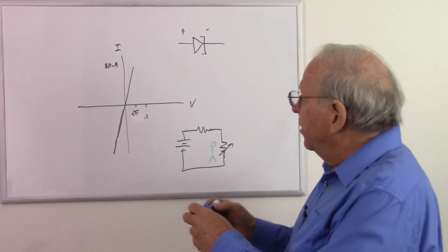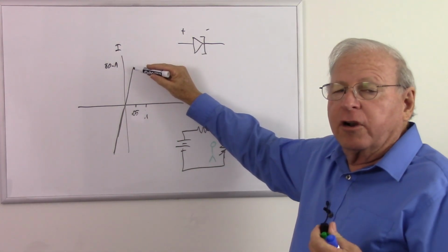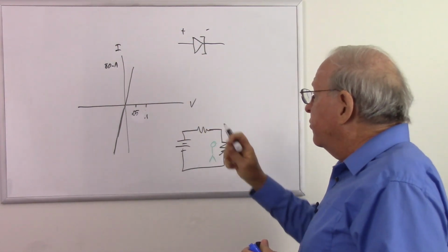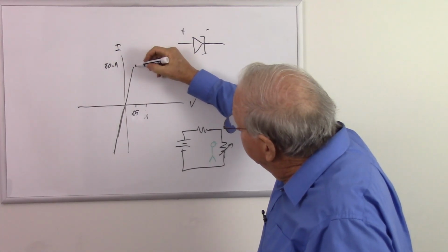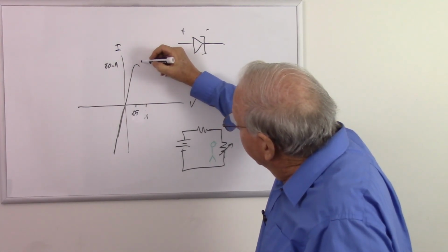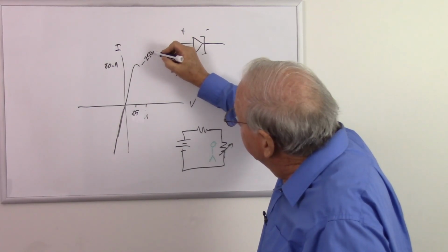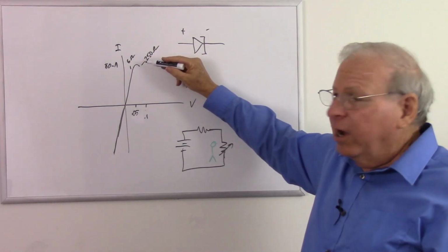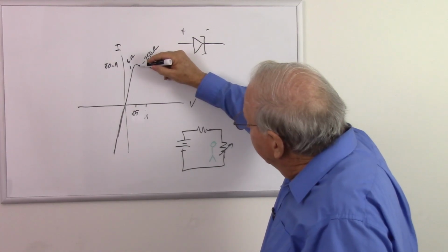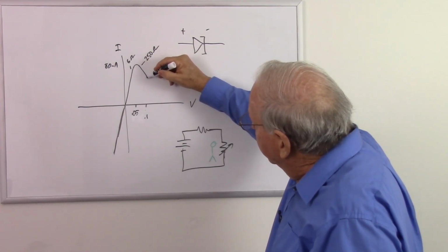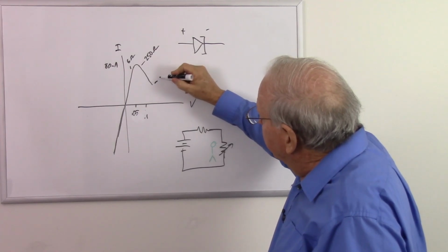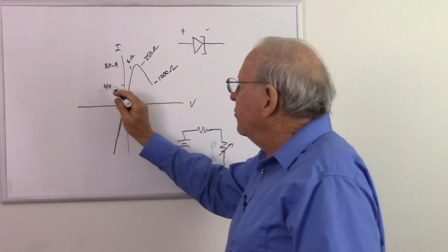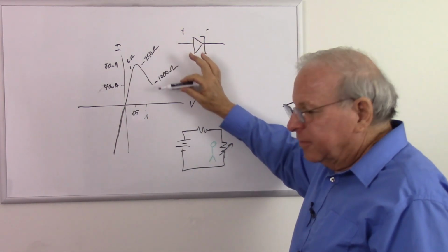So I will leave that there just for good measure. So at about 50 millivolts, his instructions are don't let the current go any higher. So as the voltage goes up, he's going to exponentially increase that resistance, forcing that current to heel over. And around here, we're going to be something like 250 ohms, where over here we were about 6 ohms. So our resistance is going to go up, and as we increase our voltage, the little green man is going to increase his resistance exponentially, so we get to about here, and he's increased it to about 1,000 ohms, and our current has gone down to maybe 40 milliamp. I may not have these numbers exactly right, but this is going to be pretty close.